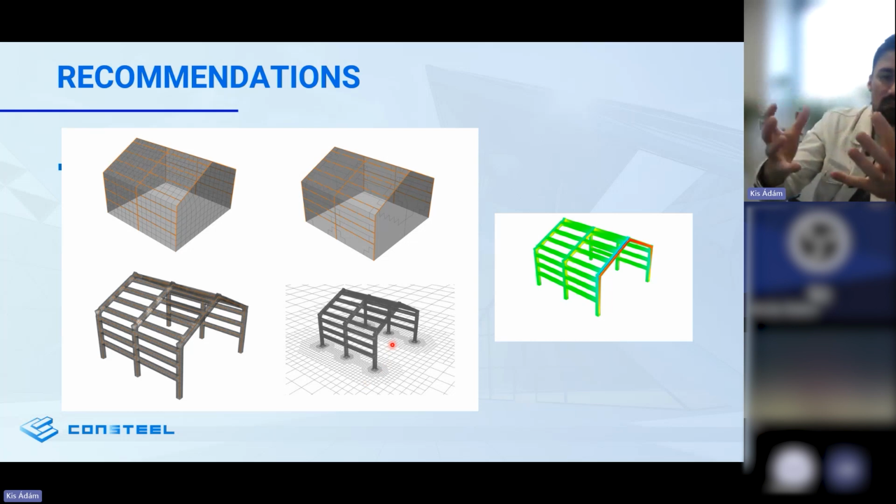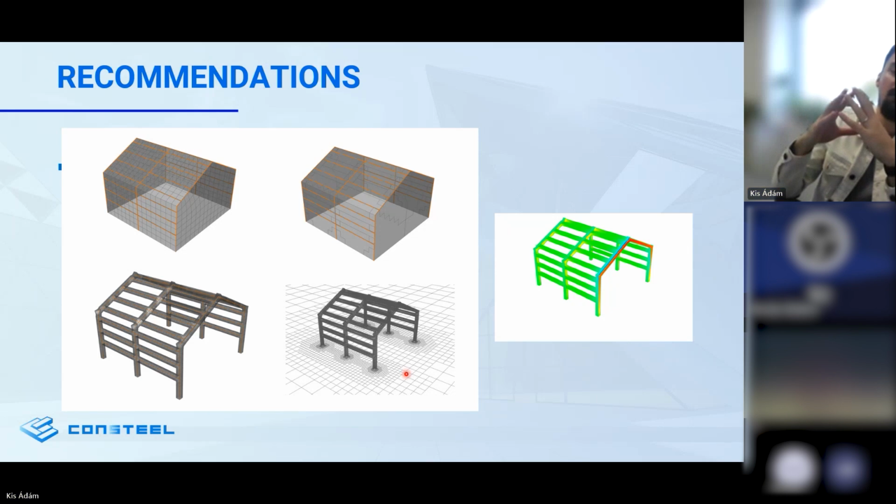So we have to wrap all this structure into a closed solid, because again, OpenFOAM and CFD in general, because it is a 3D spatial calculation, always require a finite volume mesh. Therefore, if we have these member type structures, we always have to make sure that they are wrapped and suitable for load creation.